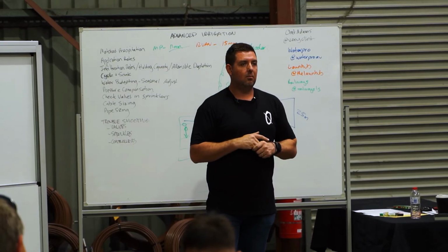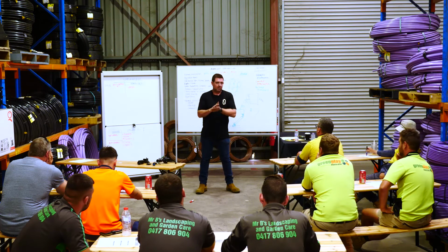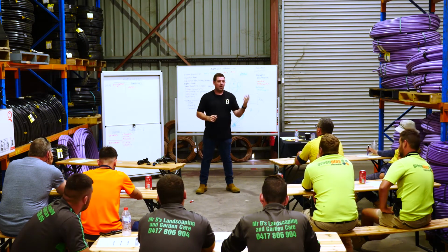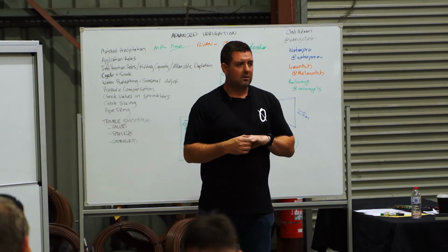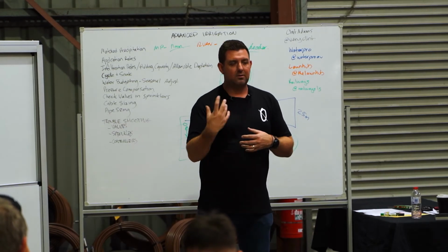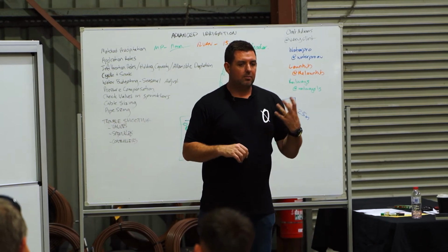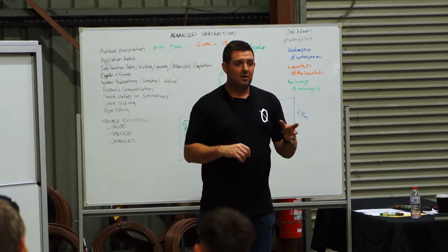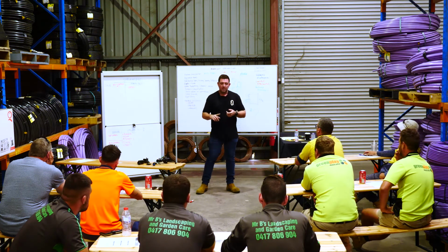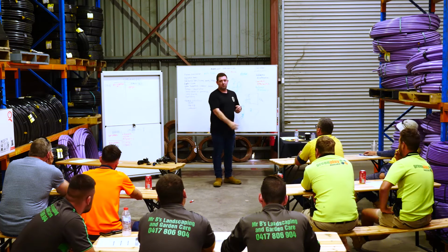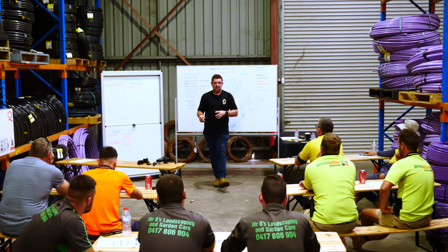And sadly, a lot of the time, the retail outlet that you deal with is going to assume that they're right and the client's wrong. And my guys straight away were like, no, he must have done something wrong. He hasn't put it in, or he hasn't done the flow test right. And the only thing that I could think of at the time is that we got him to test the system directly off the tap rather than through a hose or through a tap timer. So when you run water through a garden hose, it's going to lose flow and pressure. And if you run it through a tap timer, we discovered it loses a lot of pressure.